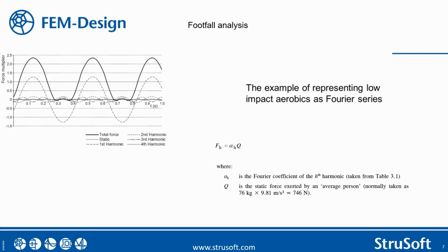This shows that the most energy goes to the first few harmonics. If we focus on the thick black line named total force, we can see that the force does not follow the half sine wave shape. This is a very good illustration of how we went from a complex force function to a series of sine waves.